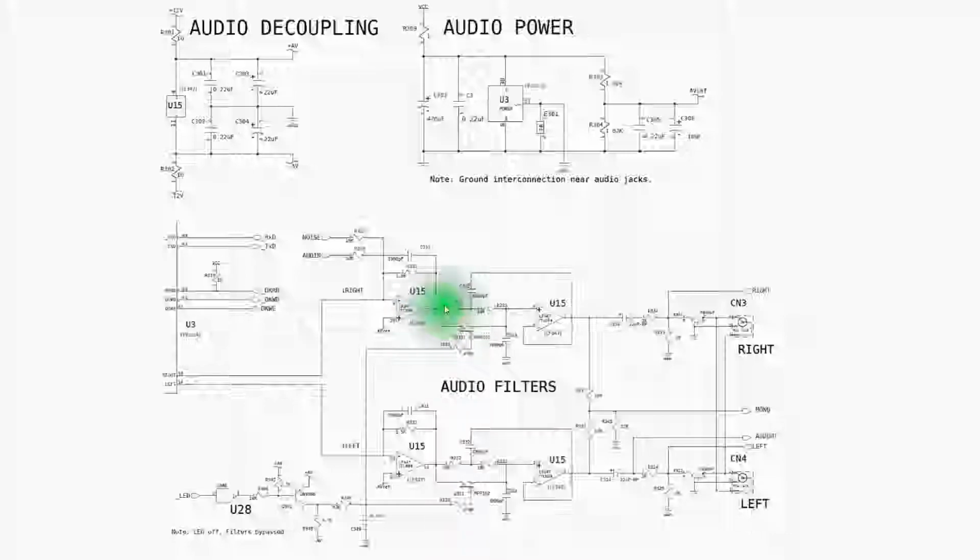So we can follow the signal on further. If I had a cold solder joint or a bad resistor here, or a cold solder joint or a bad resistor here, or open PCB traces, the signal could get to one side of the resistor and not to the other. If I got in here with the scope and I probed on this side and I saw the audio signal, and I probed on this side and I didn't, that could indicate this resistor is open. It could also indicate there's a cold solder joint on this side or a cracked solder joint, and when I'm putting pressure on it with the oscilloscope probe, it's making contact. So although that's suspicious, I'd have to look at that a little closer. The same thing goes for this resistor, and this resistor.